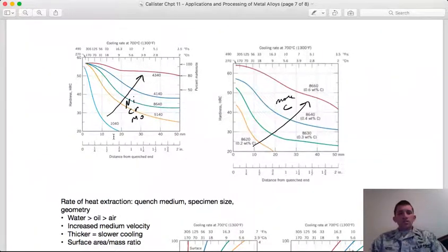You see that the hardness drops off very quickly. Within three-quarters of an inch of the end, you're essentially at 20, so you drop by maybe a factor of two-thirds. But as you add more of these alloying elements, things like nickel or chromium or molybdenum, your hardenability is increasing. So you get up to here at a 4340, and a full 2 inches away from the end of the specimen you're still at 80% martensite. Compare that to plain carbon steel, which is like 1/8 of an inch. That's 16 times as deep, with the addition of these alloying elements.